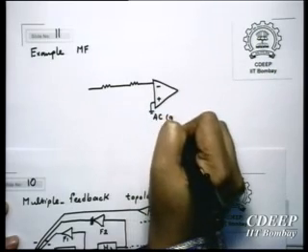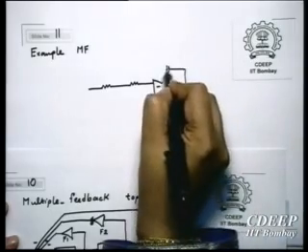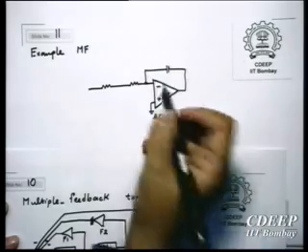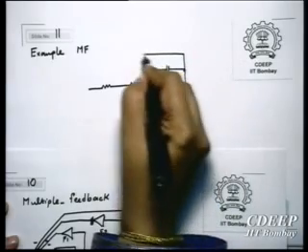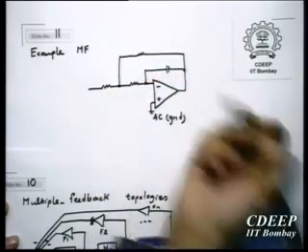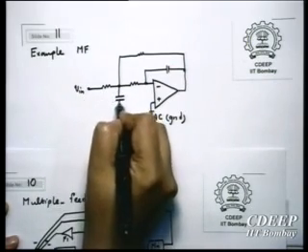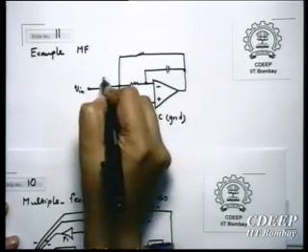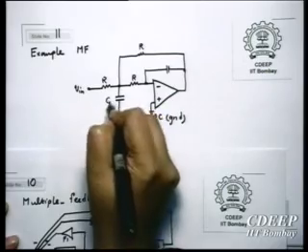This is AC ground. Everywhere when I draw it, it's AC ground. So in DC it will be reference voltage. So see, this is the integrator. Now there will be another feedback by this resistor. And this is the R, C1, C2.